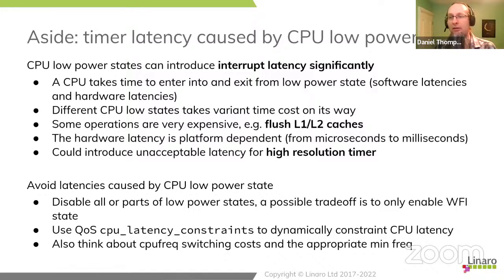So it's not that power saving techniques are invalid in real-time systems, but they add an extra hazard that you have to analyze and mitigate. So we want to say that quite loudly, and particularly the costs of entering and exiting these states will contribute to latencies.